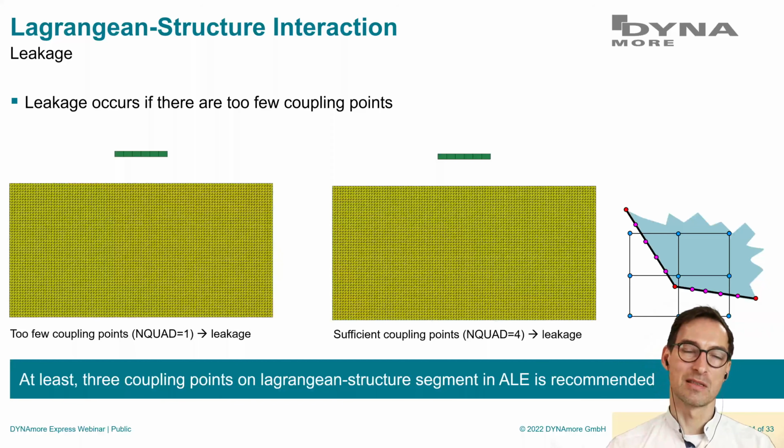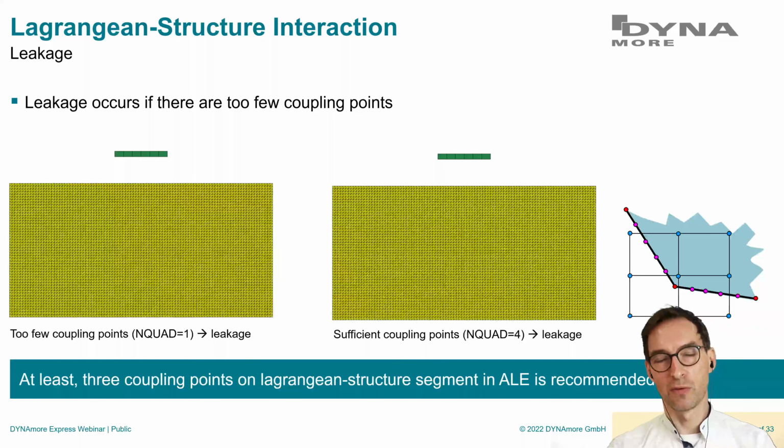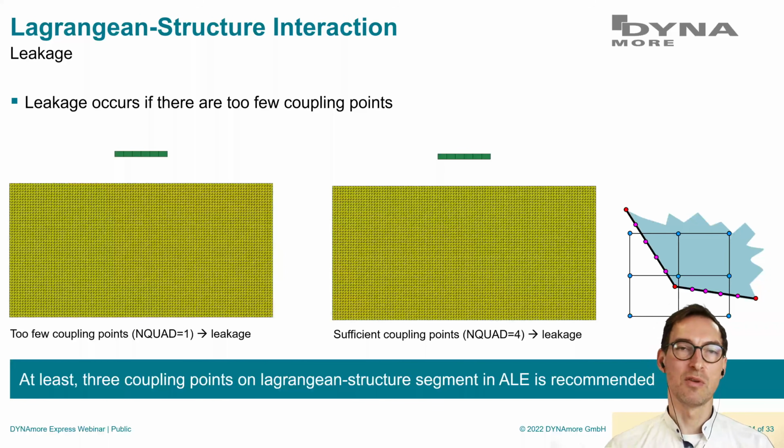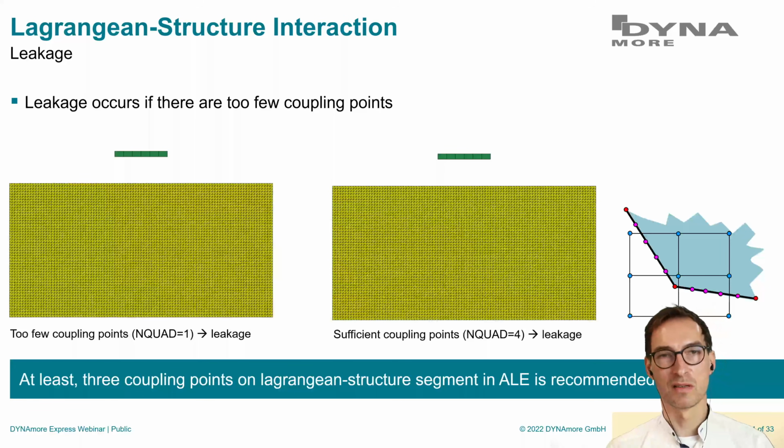Always have this Lagrangian step and think, if I apply a Lagrangian step, the nodes will deform and then be corrected back again. For you from the outside, it looks like the material is moving inside of the mesh, but it's not true. In the first step, there's always a mesh distortion. And if you prevent mesh distortion or material movement, then this is how you define your boundary conditions.